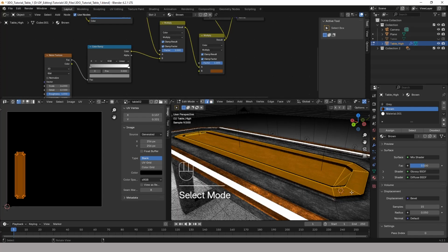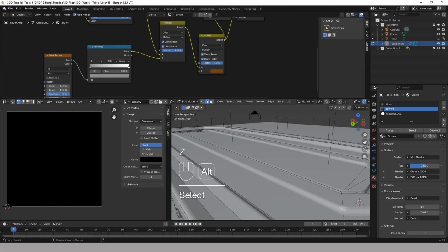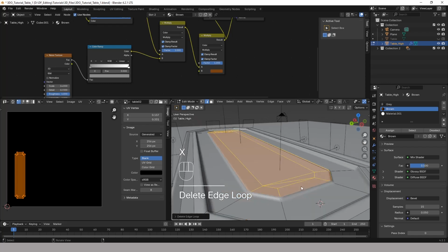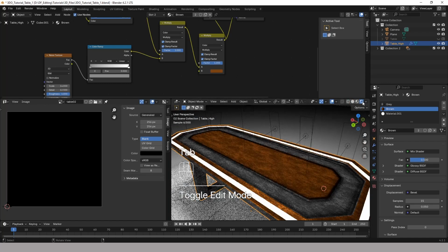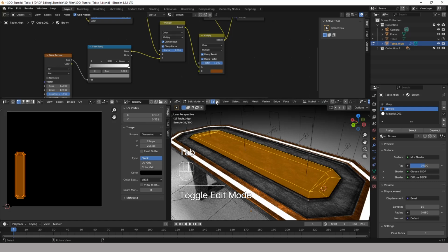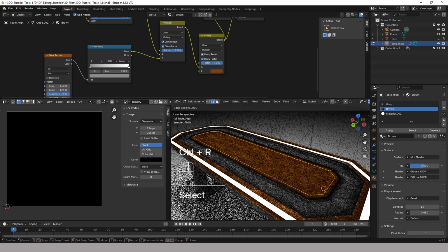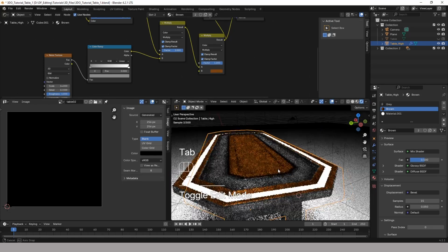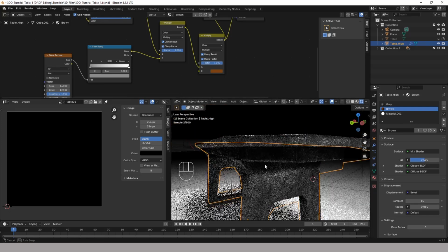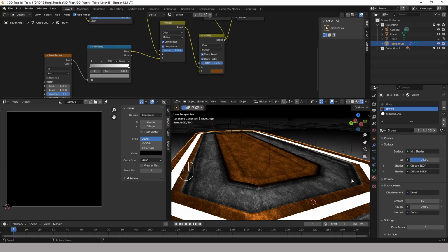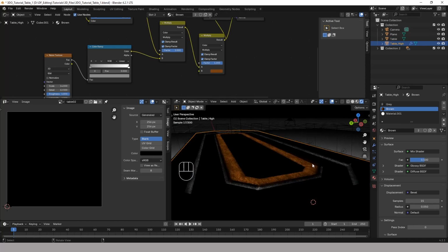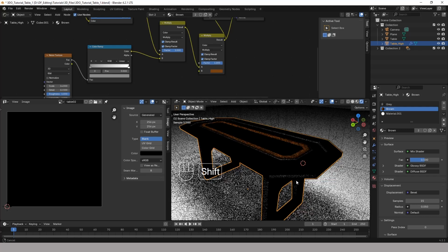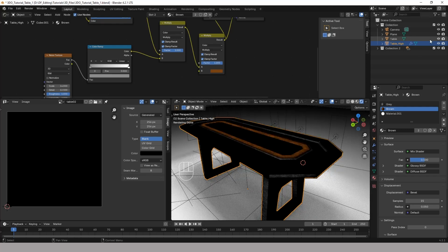And we've got one edge loop up the top here, which we probably don't need at all. Something like that. So we're still getting the detail, but there's less of a discrepancy between the shape of the two meshes. If one is protruding through the other to some extent, that's fine. I'm going to cover the setting to make sure that that works within the bake.